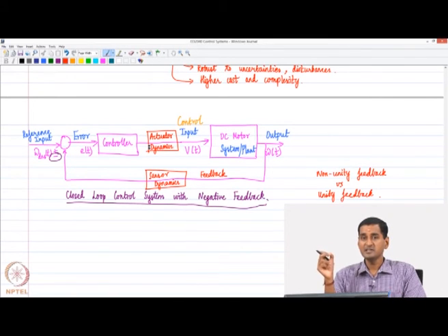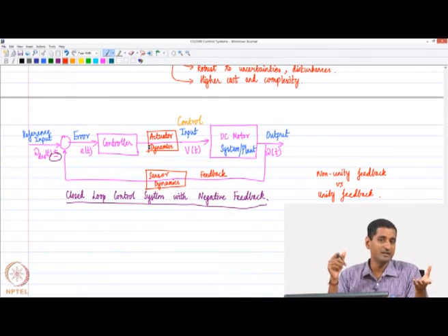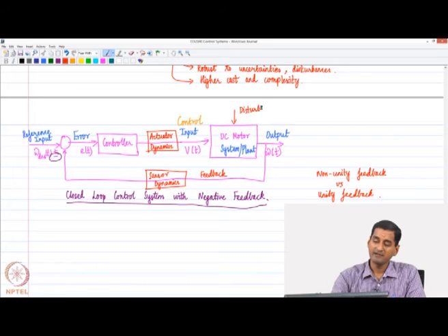So, the controller may say provide 10 newtons at this instant of time, but then there may be a small response time before the 10 newtons is actually realized in practice through the electric motor and drive system, right. So, if that is important, then we need to figure in what is called actuator dynamics in the design process. Okay. And sometimes we can have disturbances coming into the system, right. Let us say I have a sudden load that may come on a DC motor, right.